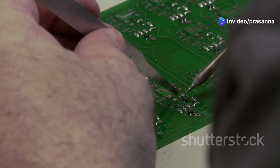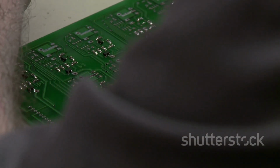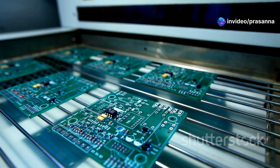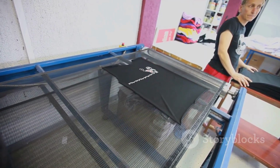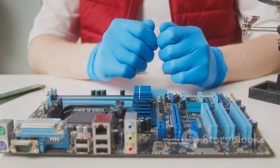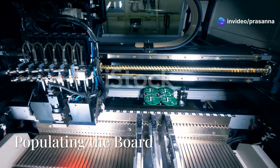Once all layers are stacked, a solder mask, a protective layer of polymer resin, is applied to the entire board except for the areas where components will be soldered. The solder mask prevents accidental shorts and provides physical protection to the traces. Finally, a silkscreen layer is applied using ink or epoxy to print component outlines, labels, and other markings on the board. This layer helps technicians during the assembly process and provides valuable information for troubleshooting and repair.